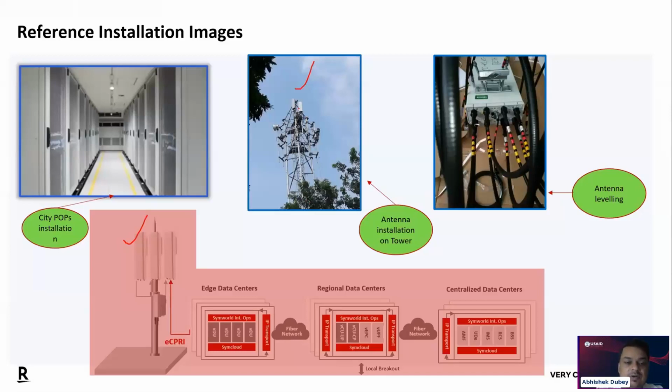Okay, there will be always a location to install the antenna that you need to follow, and also you need to follow the orientation of the antennas. It should not deviate even 10 degrees from the original plan.